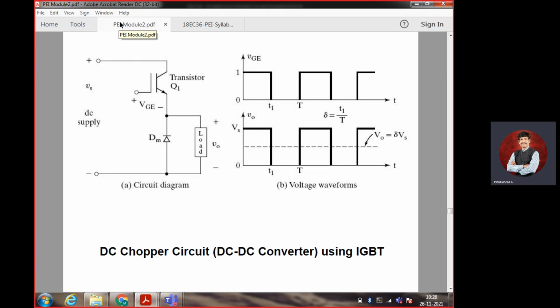It may be any time, it may be any interval. Switch is closed for 5 seconds, switch is open for 2 seconds. Or switch is open for 2 seconds, switch is closed for 5 seconds, depending on the requirement. Similarly, after this, I will open 1 second. So this is your T on, this is your T off, and this is T on.